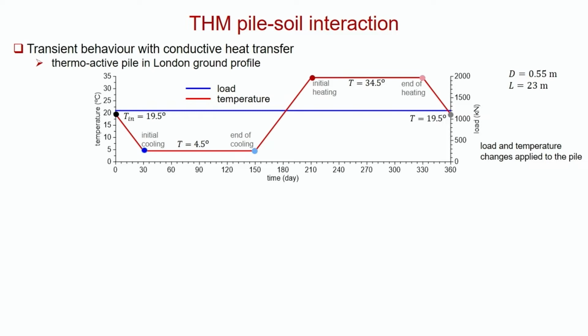All you need to do is you take the coefficient of expansion of the concrete, which is about 8 times 10 to the minus 6. You multiply it by the pile length, and you multiply it by the temperature change, say 20 times 20, and you get about 3 millimeters of movement of your pile, so it's a non-problem. Well, they're forgetting the fact that you're heating up the soil as well, and you're doing various other things. So it's not a simple problem.